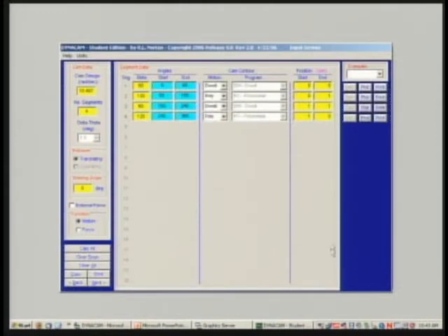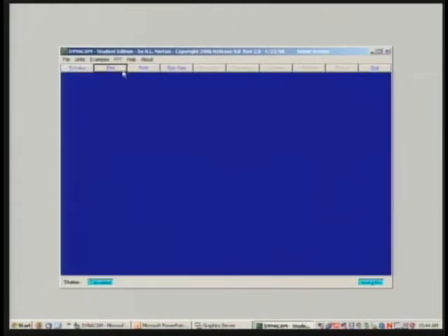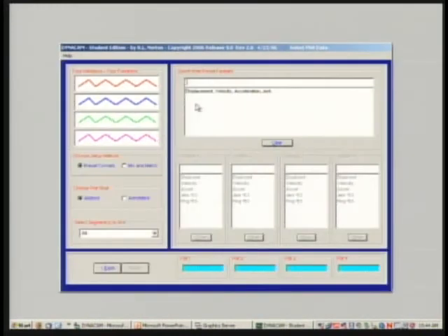So now I have a new design. Let's go now to our plot screens. On the way there, we see our continuity condition. Notice that between the first dwell and the rise, we have discontinuous jerk, but from the high dwell to the fall, we have continuous jerk because we told it to be so with our polynomial. Let's look at the plot screens.